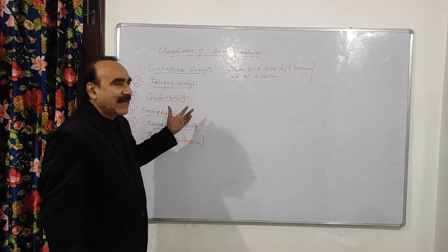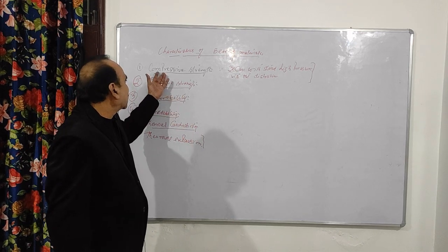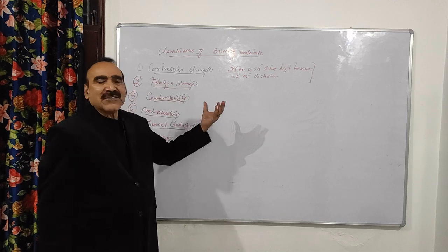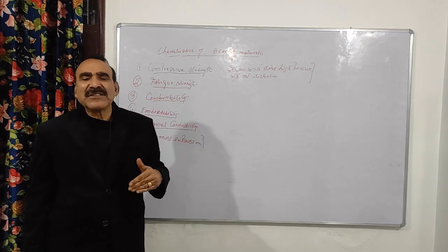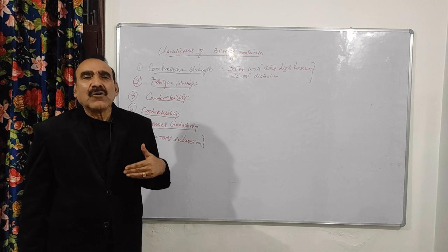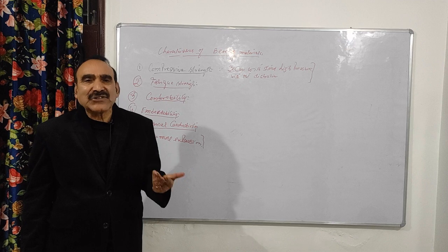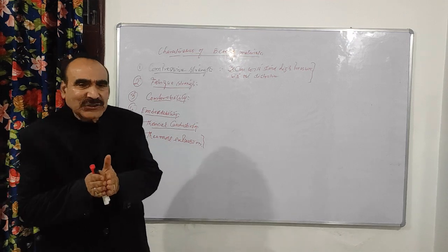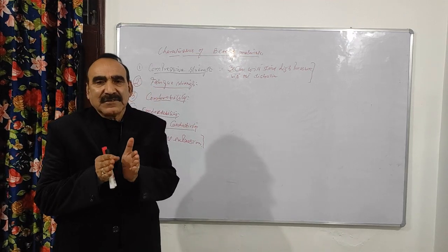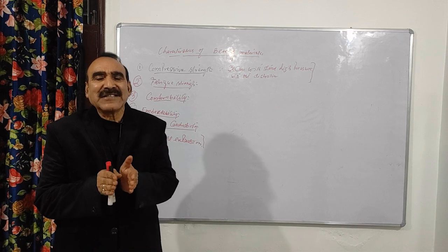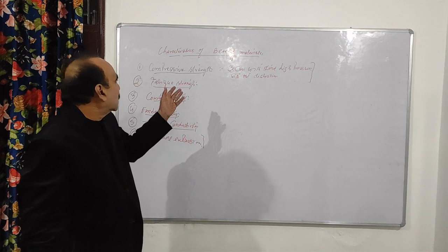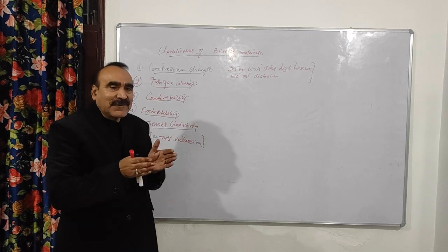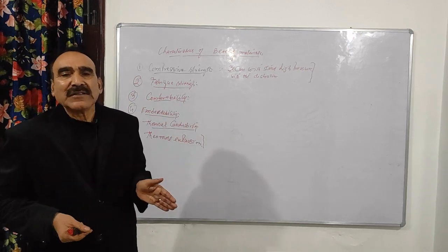So these are a few characteristics which I have described to you. Compressive strength should be high, so that it can withstand high pressure. Fatigue strength is also needed, so that it will withstand repeated load and the fatigue formation that results. I also told you about conformability. Conformability is the ability to adjust: due to deflection, due to misalignment, there is a small deflection. So the bearing material characteristics should be such that it will adjust the small deflection or deformation, right?